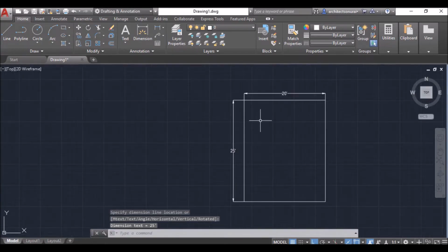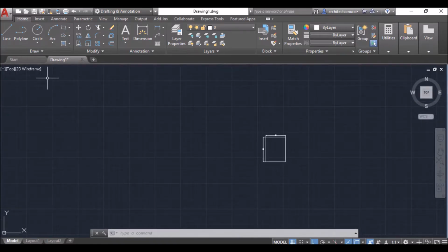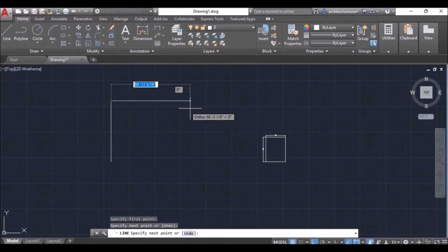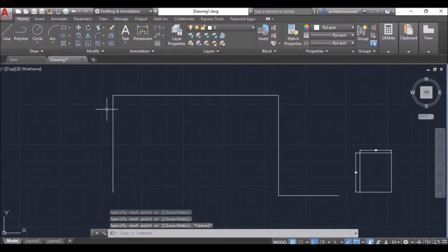So this is the use of the ortho command, and you can draw straight lines. After that you can draw many shapes using line. You can draw a wall, I will show you. Suppose you want to draw a 9-inch wall, so you will take this single line. I will tell you in depth about modifying tools later. You have to offset this single wall line by 9 inch to make a standard wall. A standard load bearing wall is 9 inch. So I will enter offset.